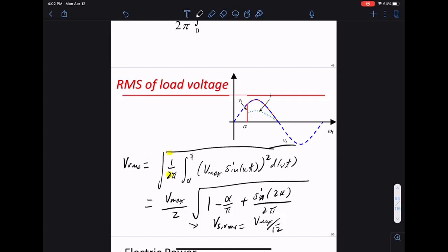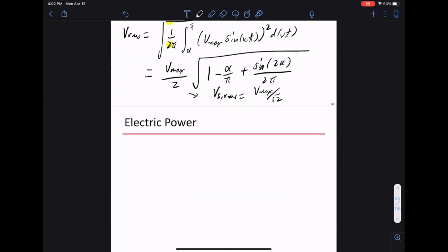Okay, all right, good. So let's now actually go into power. Again, VRMS is important because I want to talk about power in terms of VRMS squared. So power is V RMS squared over R. This is for after rectification: you still need to square the root mean square of the voltage. The root mean square of voltage relates to power, not the average voltage.